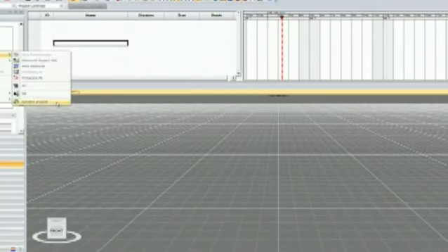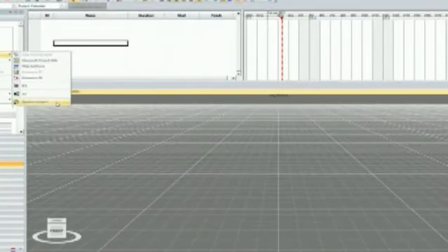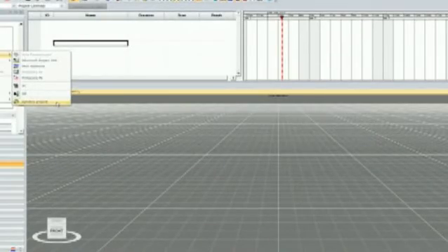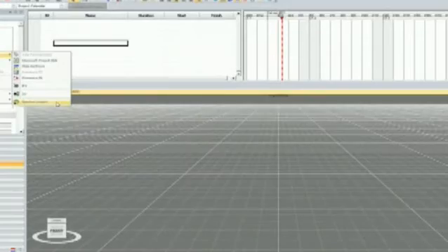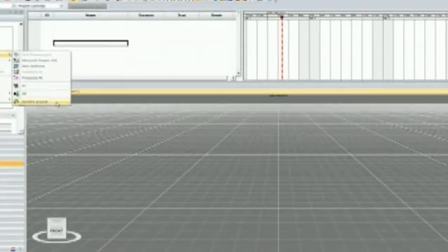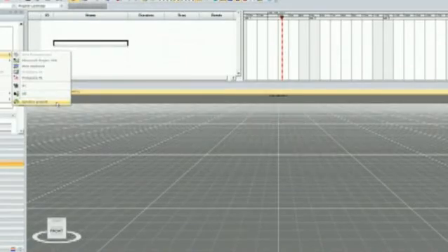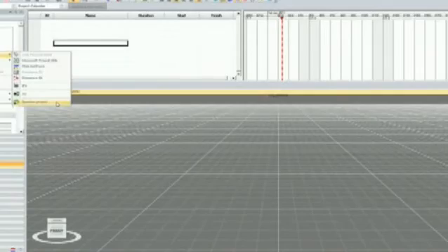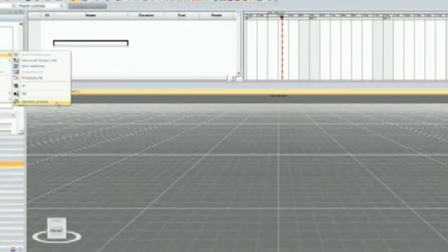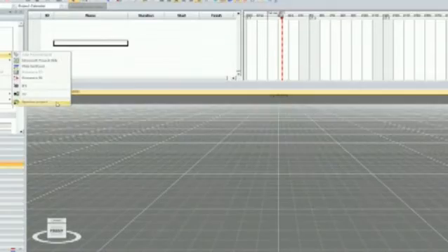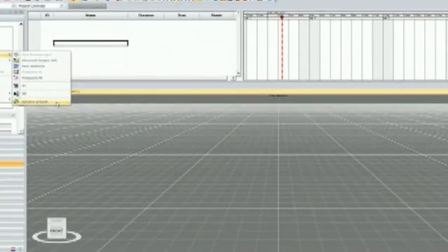So with a Synchro project, I've got a crane, I've got the laydown area predefined, I've got the schedule to erect it and deconstruct it, pre-packaged and pre-canned sitting off to the side. And when I use that crane, I can just bring that Synchro project into my project and say, okay, where's my laydown area going to go? It's already predefined how much space I need, and I can figure that out. So pre-can things on projects where you've got a lot of things happening, you can have a schedule in 3D in a Synchro project. If it's a large hospital, you could have two or three different Synchro projects that you could then bring together for a global view of the entire project.